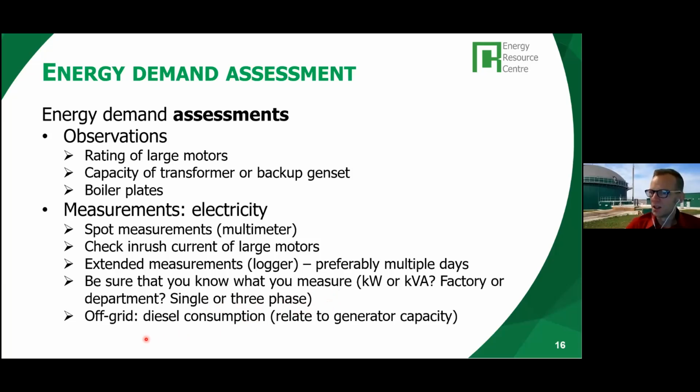For off-grid systems, it's sometimes possible to measure the diesel consumption, usually on a daily basis or a shift basis. And if you then also know the generator capacity, then you can, let's say, calculate more or less the loading rate of the generator, and therefore more or less the efficiency.